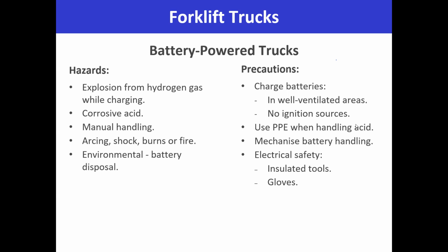What are the precautions? Obviously, make sure that the batteries are charged in a well ventilated area, adequate ventilation is there, and there should be no ignition sources near the battery charging. Use PPE when handling acid, mechanized battery handling, and protect yourself using electrical safety, such as insulated tools and gloves, etc.